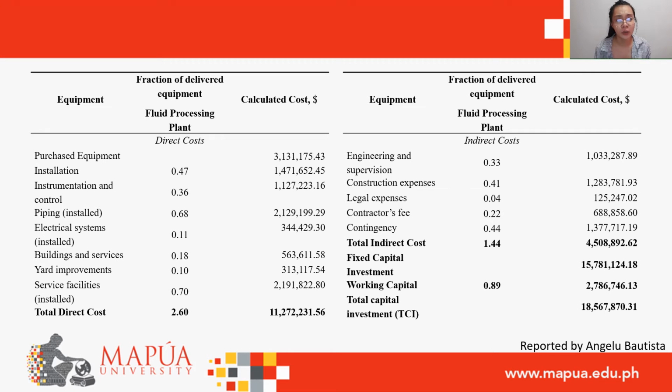Firstly, it is important to note that we define the type of plant under consideration as fluid processing plant. The reason behind this is that from literature, as stated by Ray and Johnston, sometimes it can be quite tedious and difficult to categorize a plant, especially with multiple processes. However, based on the adopted process scheme of this design project, which is the modified Kolbe-Schmidt carboxylation reaction of Bayer, that is the Bayer process from patent literature, carbon dioxide sparging in a fluidized bed reactor.